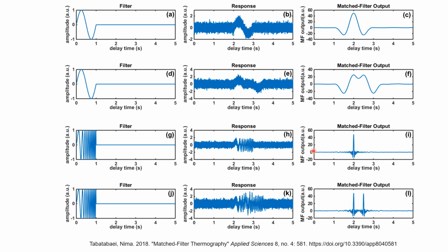You can see that we have similarity here, but it's less. Similarly here, it shows you that there are two signals, two multipath components that are received. So the beauty of the matched filter allows you to make decisions in these noisy signals. And you can see that the output of the matched filter is much easier to deal with.